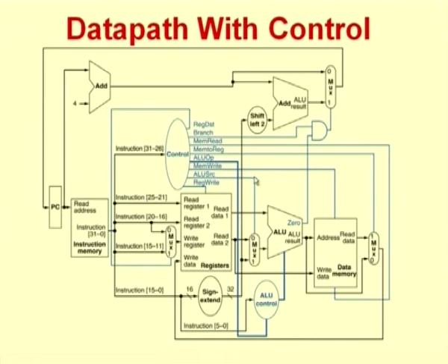If it is a load or a store memory instruction, then we know that the value will have to come from the sign extended part, otherwise it will come from the register. So depending again on the type of instruction, the signal can be generated, and then a register write operation will be generated from the control logic. With the control signals generated from this control logic, you can have the complete control setup.